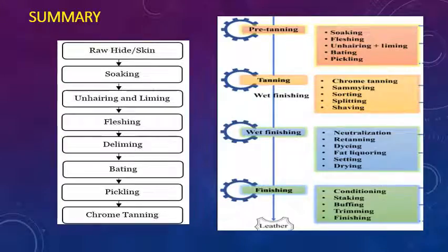So now we are at the end of today's lecture. These are the steps we started with. We have discussed in this lecture the structure of skin and the different steps of making leather from hide. There are pre-tanning stage operations, then tanning operations and post-tanning operations. In the pre-tanning operations, the hide is made ready for actual tanning through different steps, and the most important are soaking, then liming, dehairing, bating and pickling. And then the actual tanning, which is vegetable tanning and chemical tanning.